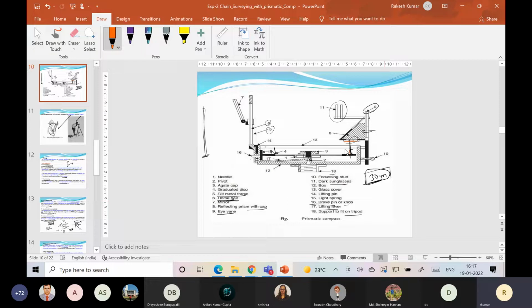So we are indicating 180 degrees at that point. Sir, may I? Yeah, please. Sir, because now if we see the reading from the prism, it will directly give us the right angle. We don't need to do any calculation. It will give the magnetic bearing. If here it is 0, then whatever shift is in the angle, we will directly get the angle under the prism.